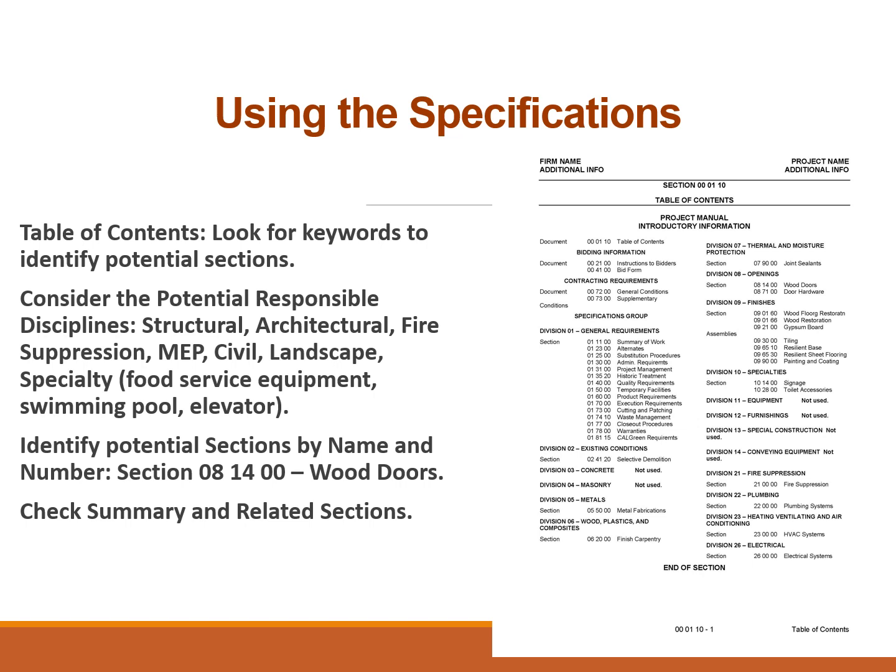Usually, if you want to consider the divisions of the divisions in the package, you'll notice that once again, in this particular case, none of the structural sections, concrete, masonry, metal, or wood and plastics, have any real structural sections to it. So you can tell right from this table of contents that this project does not include structure for a building. This is purely an interior project. The existing conditions are selected demolition, which would also be interior, and you'll notice there's no division 31 or 32. So just by looking at the table of contents, you can get an idea of what kind of project this is, which you should technically already know anyway.